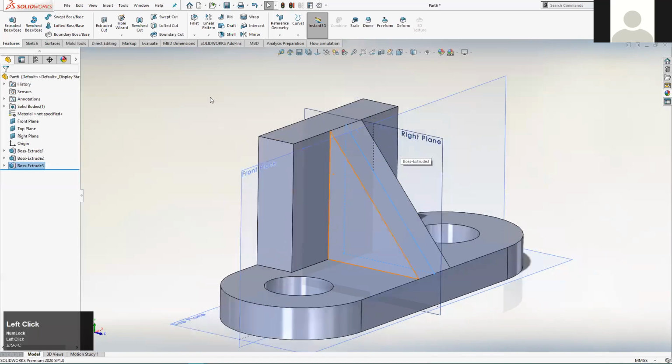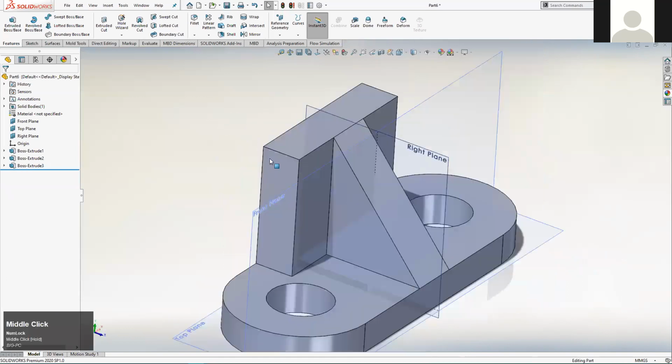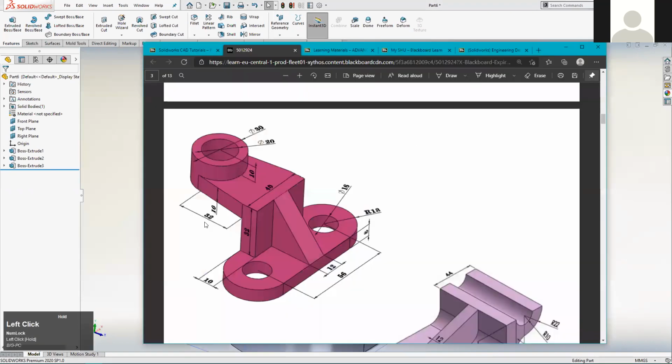So we can OK that one as well. And then, so we're nearly there. So what are we going to do next? We are going to create this sort of tapering block of material. The way that I've decided to do that, and again, there are multiple ways that you could set this feature up, but the most logical one to my mind is again just to create a 10 mil extrude. So you can see it's 10 mil thick of the correct boundary shape that has a semicircular arc at one end, and it's smaller at that end, so it tapers down from the width of our block that we've just drawn to that end.